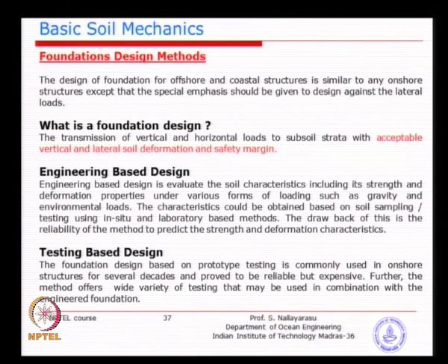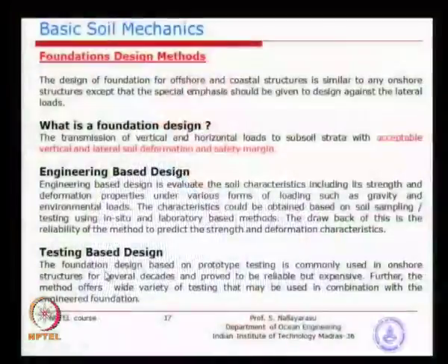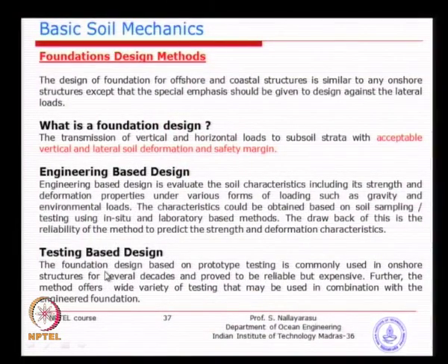If they match very well, it is very good, because your assumptions in your analysis or your calculation are matching well with the behavior at site. If it does not match, then there are corrections to be made. What we do normally is, you take the correction factors back to the engineering room. If the capacity predicted is higher, you correct it to bring it down.